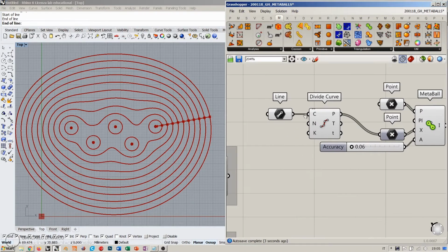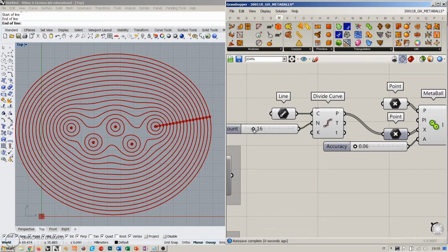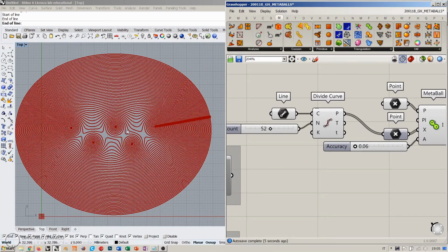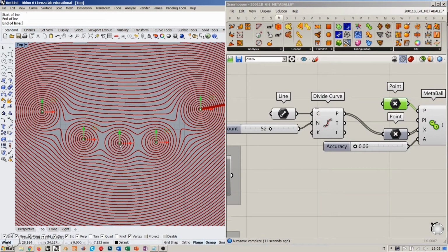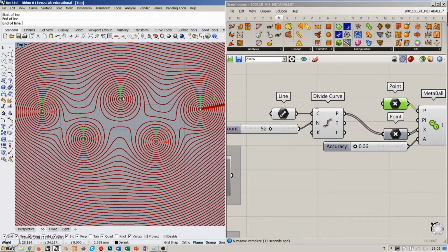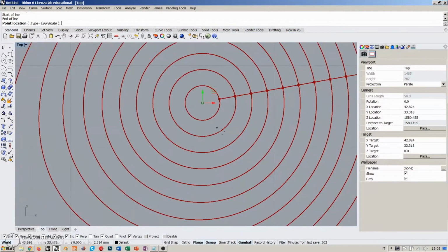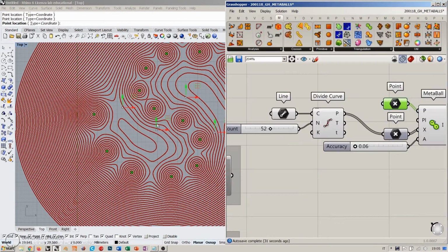So you see that now we have a more regular aspect for our isocurves or Metaball curves, and a more controlled graphic coming out of this Metaball component. We can always work with our points, or we can also specify multiple points, like having the first one more or less coincident with the existing one, and then create some weird thing like this.